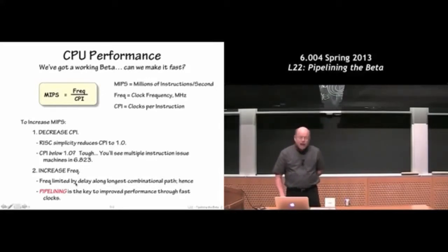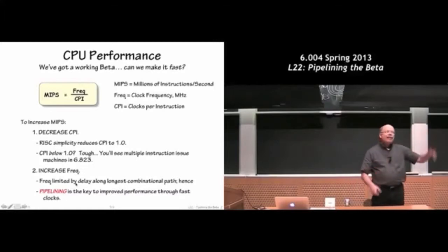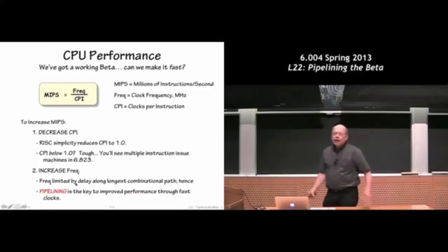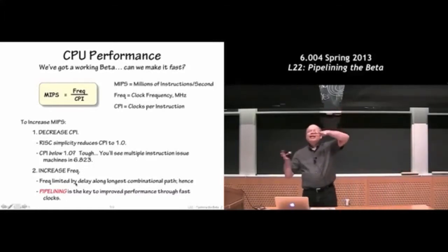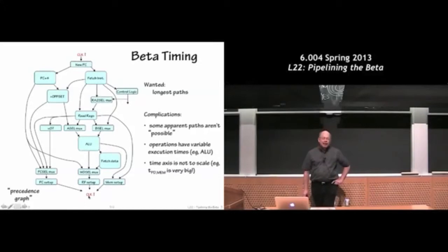But today's task is to figure out how to make our clock cycle faster. We've got a basic strategy. It executes instructions. We have this big piece of logic. If you look for the tPD as you go through the entire picture of what happens after the rising clock edge, think of all the things that need to happen in terms of executing an instruction and the different hardware blocks involved. And then you're all ready to store the result in the register file at the end of the cycle.